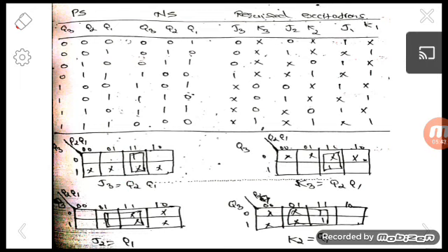And we know that by writing the values of J3. Here we are considering Q3 Q2 Q1 as the variables, and first we are going to draw the K map for J3. For each value, for 0 0 0 we know that the value of J3 is 0, so here it will be 0 0 1 0, then x x x x. So a pair is possible here, and the expression of that pair is J3 is equal to Q2 Q1.